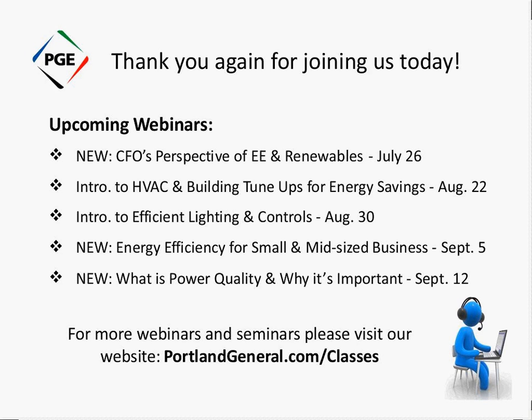Demand charge is the highest energy used in a half hour. So over one half hour, up pops your bill, and it says, here's the highest half hour use that you had. Now, the purpose of this is that the utility company has to build facilities that handle and provide you power at your highest energy use, your peak. So that number gives the utility company an idea about what facility they need to build, transformer, wire size, etc.